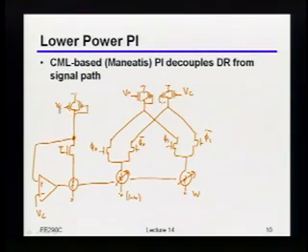So then what I'm doing is I lower that VC relative to VDD. I'm doing two things simultaneously. First, obviously, I'm reducing the resistance, just because the VGS of that transistor in parallel is increasing, or the magnitude of the VGS. Second, I'm also increasing the swing, okay? So that's really how I control that resistance, which also obviously controls the edge rate that you're dealing with. Does that make more sense now?